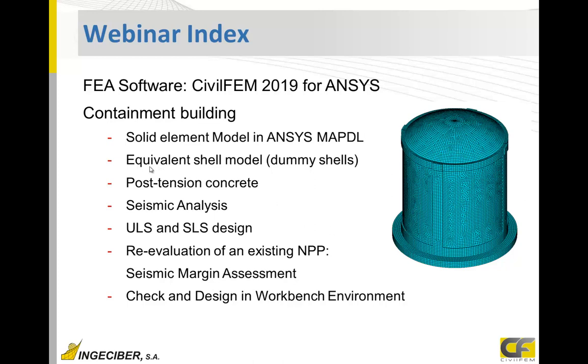Well, so first this equivalent cell model, then we will apply post-tensioned concrete tools, that is defining tendons, and CivilFEM will apply the equivalent prestressing loads to this solid element model. We will apply some other load cases, and then we will combine them. Also, we can combine with seismic analysis results, and then we will perform a ULS and SLS design and check. After this, we will follow all the procedure for a design of a nuclear power plant.